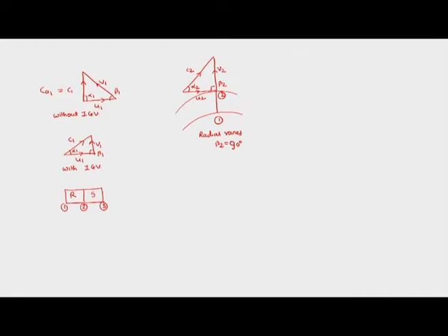After having radial blades, we had also seen that there will be backward facing blades. In the case of backward facing blades, we have a different velocity triangle. First we have U2, then V2, and then C2.